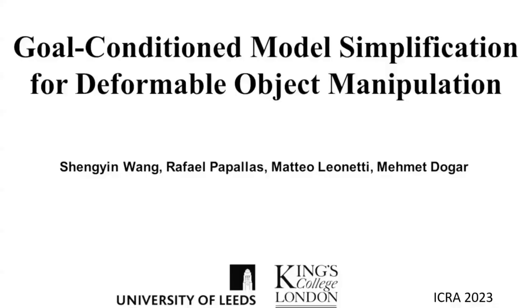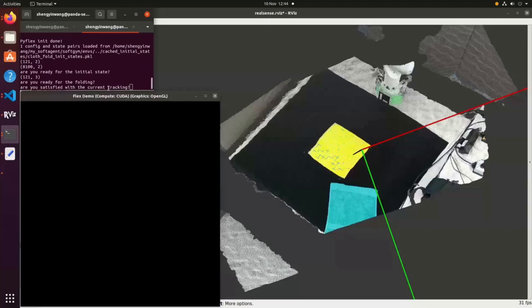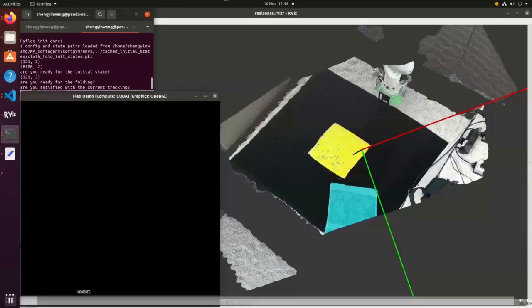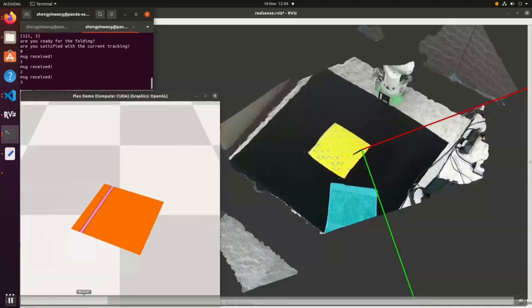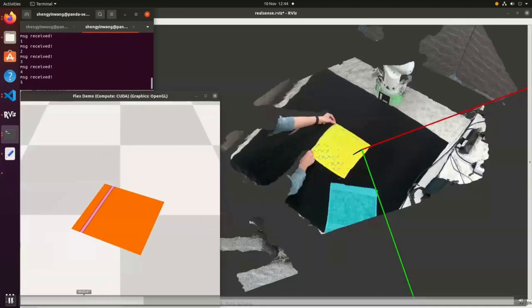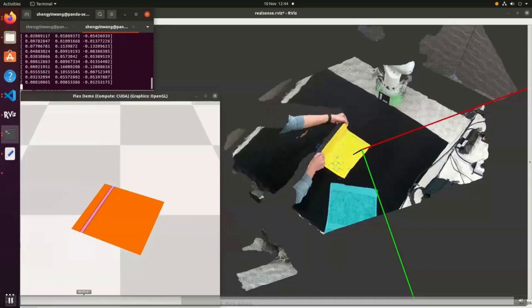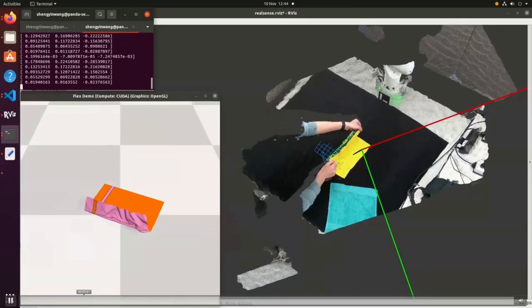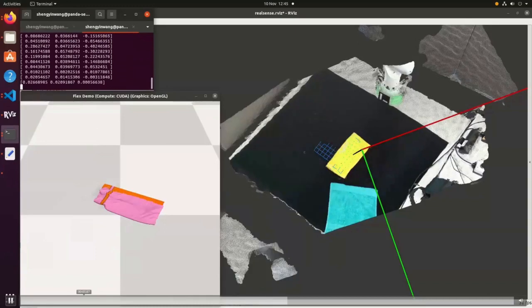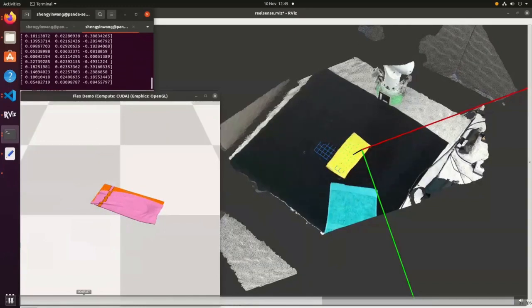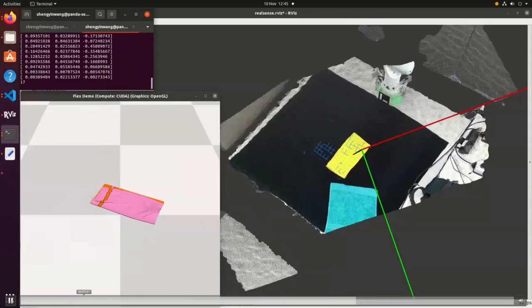So the thing is, what we have now is open, but we have recently also been interested in tracking these objects as well. So here, the very out of the oven thing that my student Schengen has been working with. So we actually want to connect this in an MPC manner to do real tracking. So we have been looking at tracking the deformable objects so that we can then run these planners in a model predictive control manner, constantly updating the actual state.